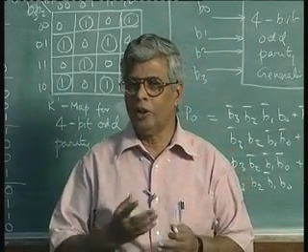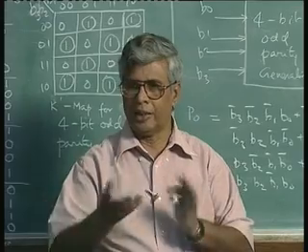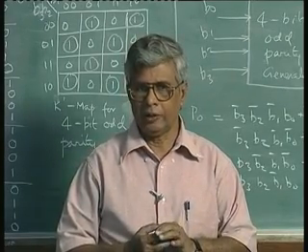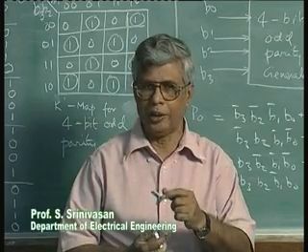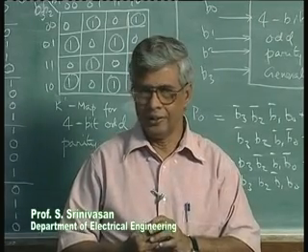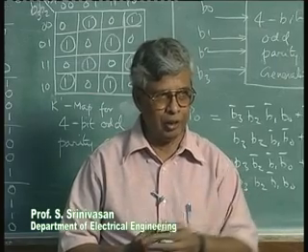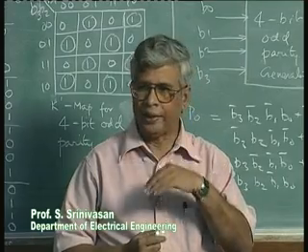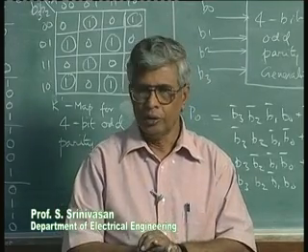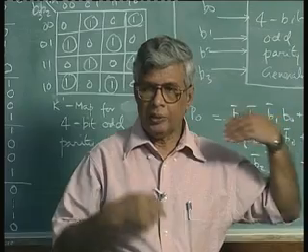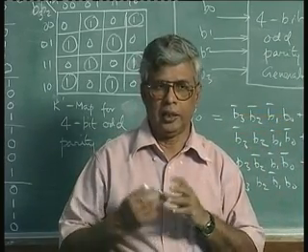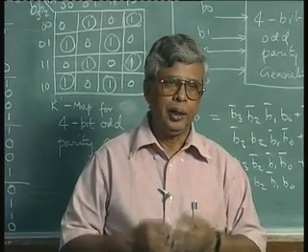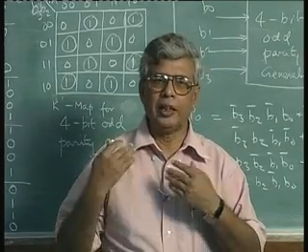Odd or even, you have to work out the exclusive OR combination slightly differently, whether you are odd parity or even parity, right? The beauty of the exclusive OR and exclusive NOR combination is one is the complement of the other. So if you take an inversion of an exclusive OR, you get an exclusive NOR. You get an inversion of the exclusive NOR, you get an exclusive OR. So because of that, whether it's odd parity or even parity, it's a question of one inversion again. So these are some of the practical circuits we use all the time in data communication: parity generation, parity checking. Parity generation and parity checking is an integral part of any data communication.